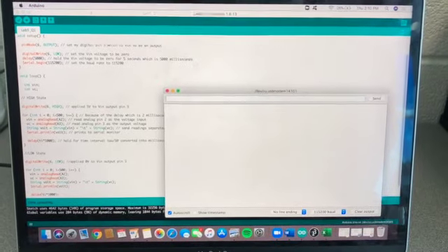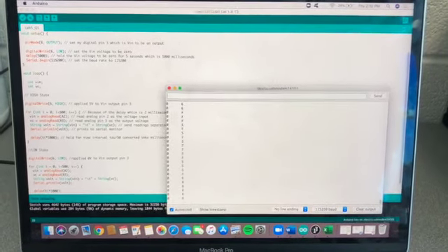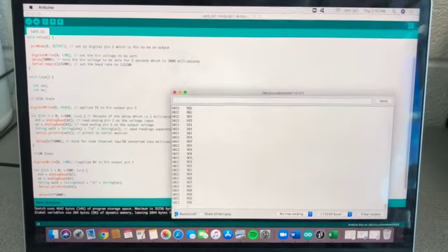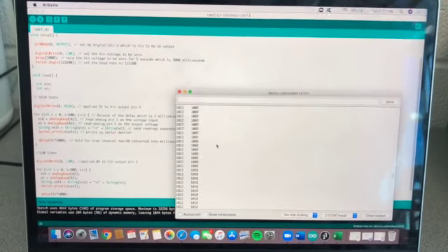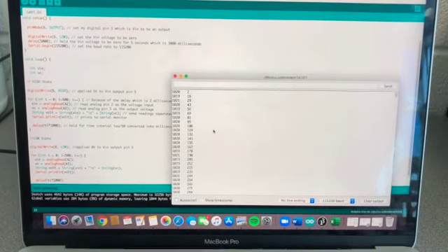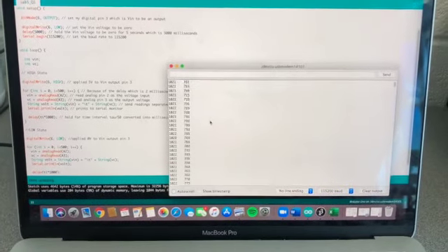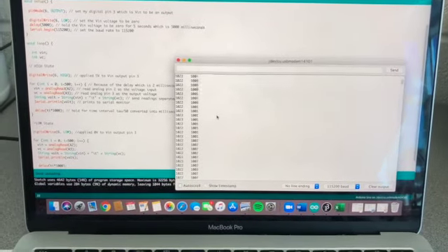The serial monitor can be seen delaying for 5 seconds before running. And for the time interval where Vin is 5 volts, you can see Vin is near 1023 for the whole time interval, and the capacitor is charging up until it reaches around 1023. Then, when Vin is 0, the capacitor gradually discharges.